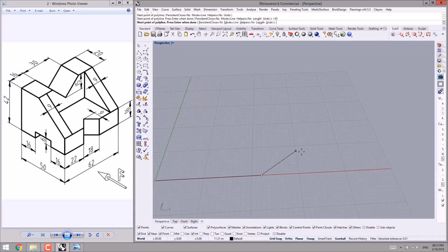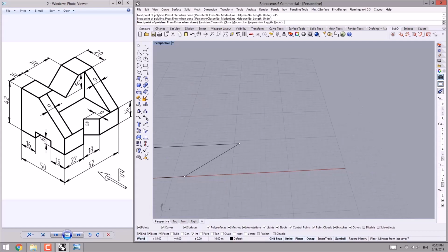And as you're concerned, the length of the line is 9 units. So I import 9 in the command line, then I press enter. Then here the relative coordinates, as you can see, are 9 and -9 along the x and y axis. At sign 9, -9. Well done.